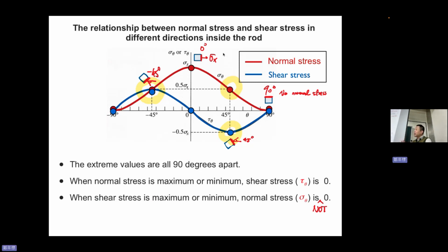So I hope you can understand that when you look at a material, the inner stress components can vary when you observe different directions. So when you find that under some loading in a certain direction there is the greatest value of sigma, it means that in that direction the material will break first compared to other directions. That's how you examine which direction of the material will break. Do you understand? You use this component to see in which direction the stress is the maximum. If it goes on like this, that direction will fail fastest. That is why materials science helps us learn which side breaks easily. Nice. Next one.